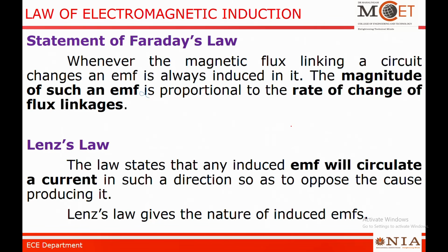The first law is Faraday's law and then Lenz's law. So now we are going to see what is meant by Faraday's law. Whenever the magnetic flux linking a circuit changes, an EMF is induced in it, which means the magnitude of such an EMF is proportional to the rate of change of the flux linkages. Then Lenz's law states that any induced EMF will circulate a current in such a direction that it opposes the cause of producing it.